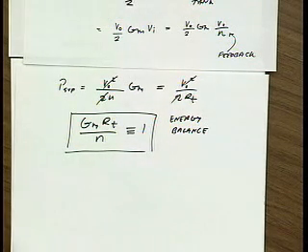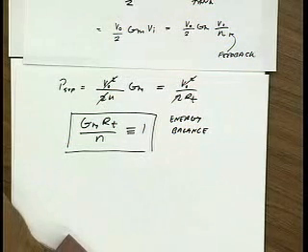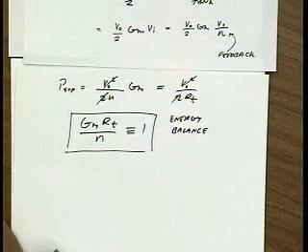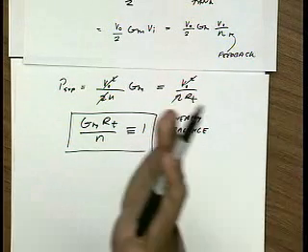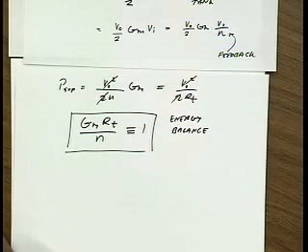So we'll go back to that linear circuit perspective just to gain some intuition. The reason the poles move, just quickly to answer your question, then we'll talk about it again later in the lecture, is because as the amplitude grows, the GM of the circuit goes down, and that means the loop gain goes down. And as the loop gain goes down, the poles tend to move back into the left half plane.